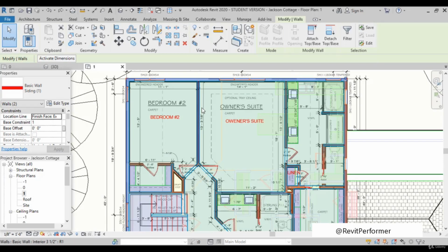If I select one more wall, like this wall also, which looks a little bit thinner, suppose after selecting this wall, it is a 4-inch wall. When I select the 6-inch wall or 8-inch wall, that is okay. And when I select the 4-inch wall, the properties are not matched. That's why it's written there: Basic Wall, multiple types selected. When we select multiple types, at that time we should not change their properties. If we change their properties, it will affect the whole scenario. So that will be wrong.